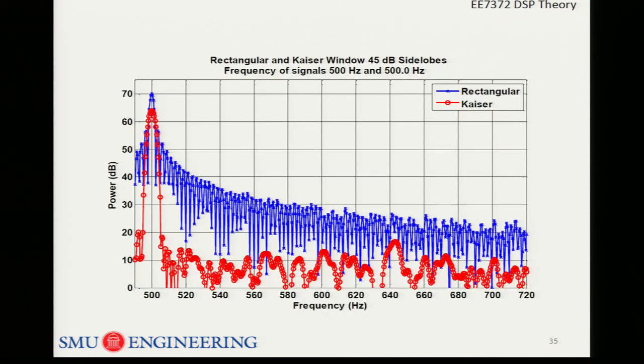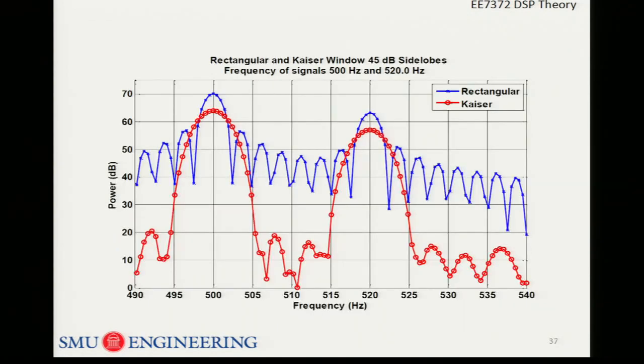So the purpose of this is to show you the effects of the side lobes and why you might want to use windowing. You might say, okay, I'm sold, let's use windowing and forget about it. Well, now there's the dark side of windowing, the resolution limitations. So what we're going to talk about next is moving these 2 close together and seeing if you can resolve them.